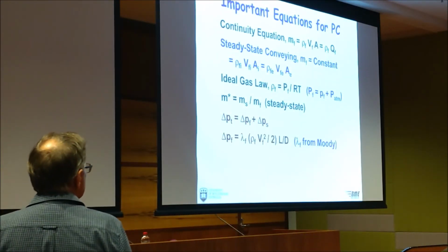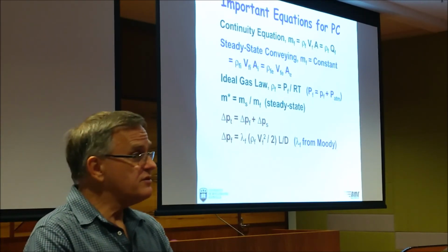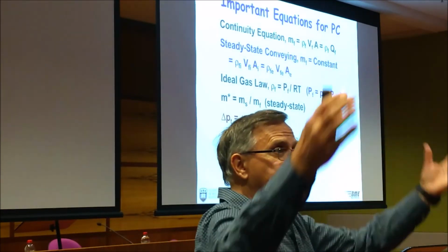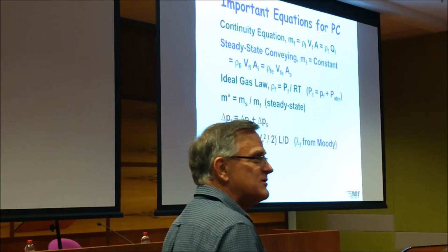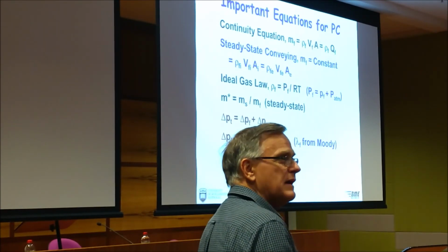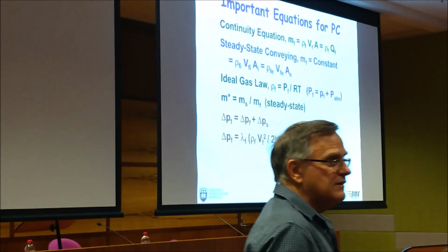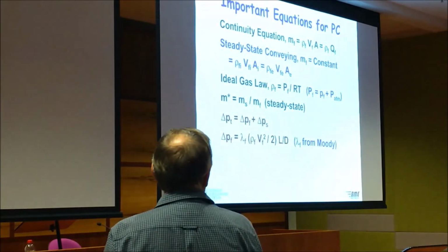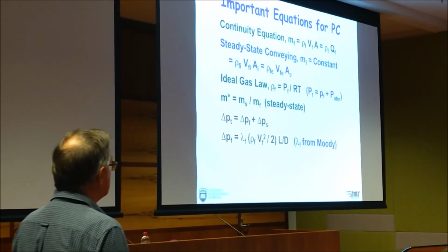So for the air pressure loss, we can use the Moody diagram to work out our friction factor. You've done friction factor losses? Liquids or gases, it doesn't matter. You get your friction factor from your Moody diagram. Some people are nodding, they remember Moody. He did his work back in 1949. He's probably dead now. But Moody is the guy that invented the friction factor chart based on Reynolds number and roughness and all that stuff. He developed a friction factor chart we use for liquids and gases.